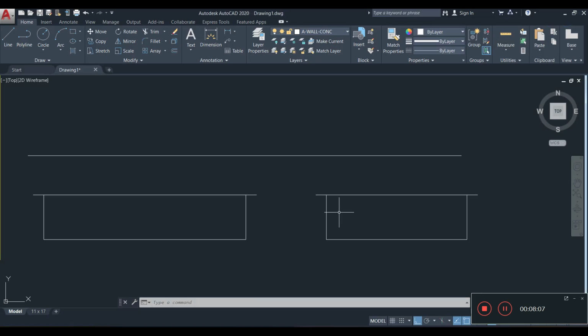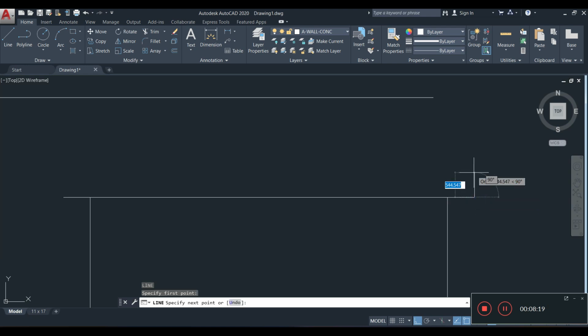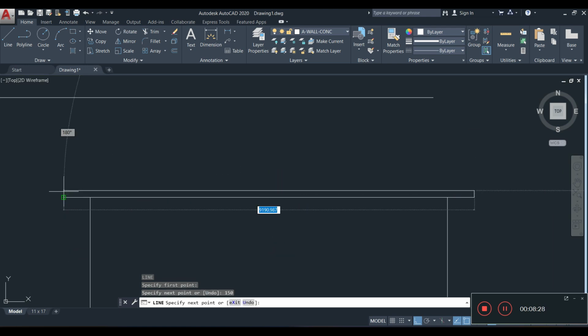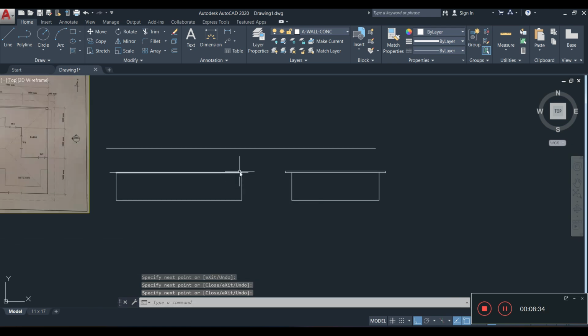So what we're going to be doing, we're going to use our judgment here, and we're going to offset this line here up by 600 millimeters. Or you could simply draw a line up from the corner here, up, not 600 millimeter, 150 millimeter. 150 millimeter is basically 6 inches. Then you'll go across. You could use dynamic tracking to guide you, and you'll get that. Now you could have easily drawn a rectangle as well. The option is yours, and you'll be fine.